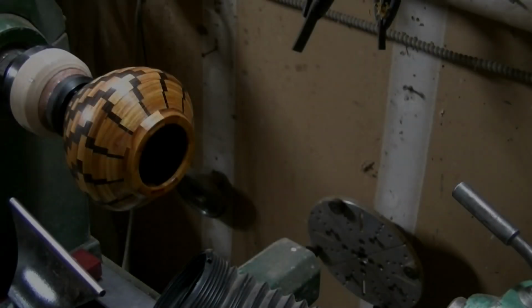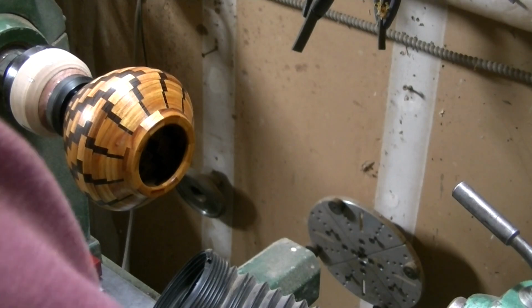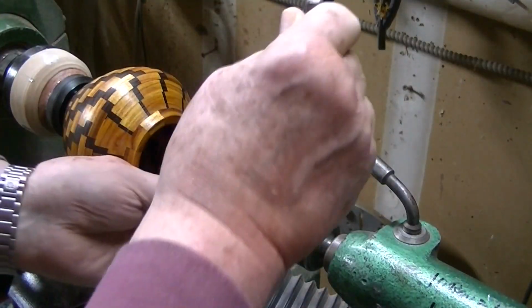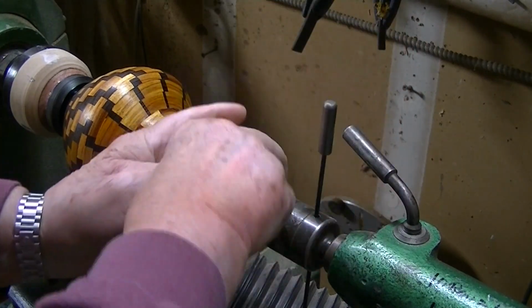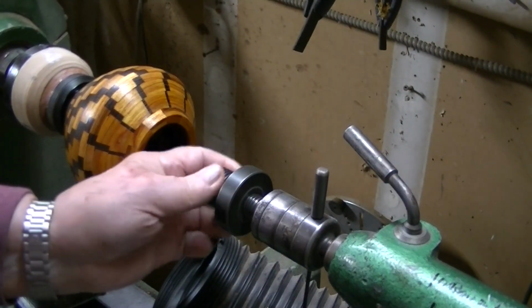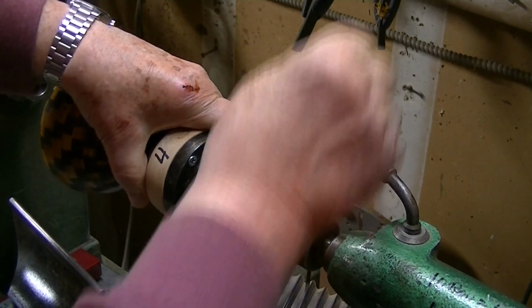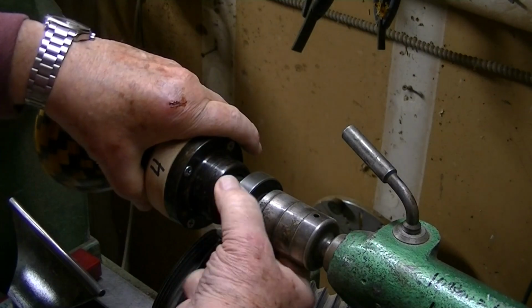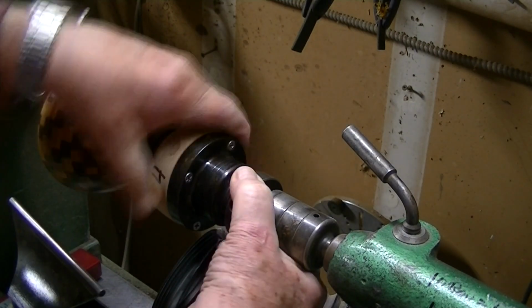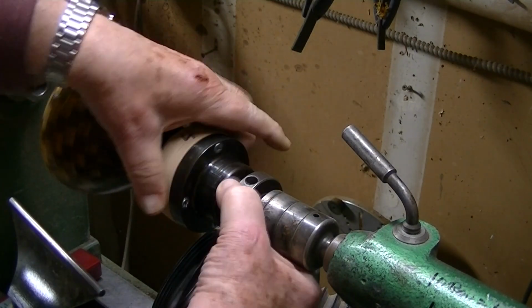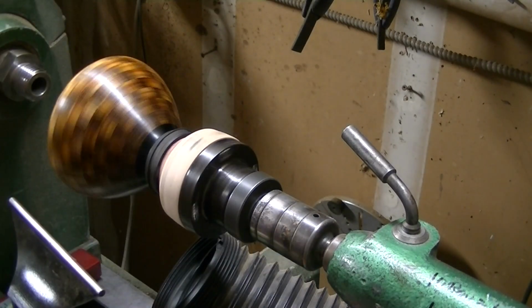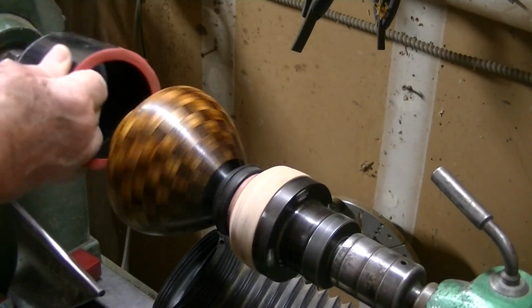And now the separation needs to occur. I need to take this project off of the glue block and free it. Here we're back to the live center system again. And I'm now going to move the vessel complete, faceplate and everything, onto the tailstock. This gives it perfect centering and gives me some holding power. And once it's mounted, I'll be able to use it with my vacuum system, which then will push it into the vacuum chuck very well centered.